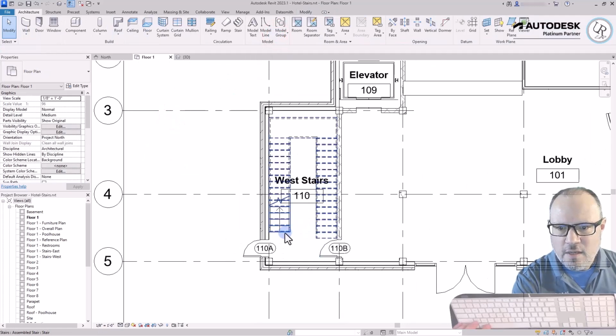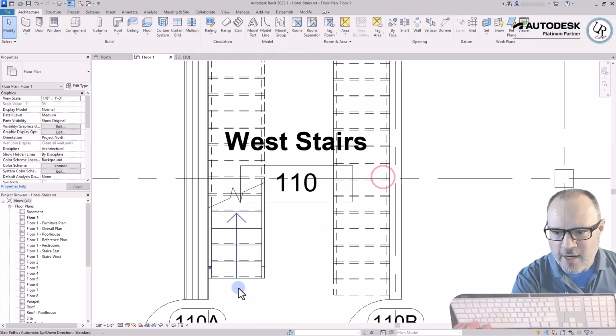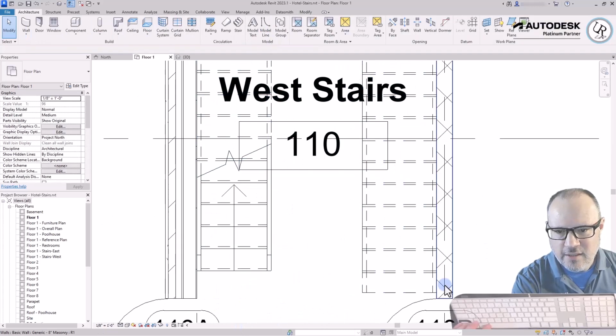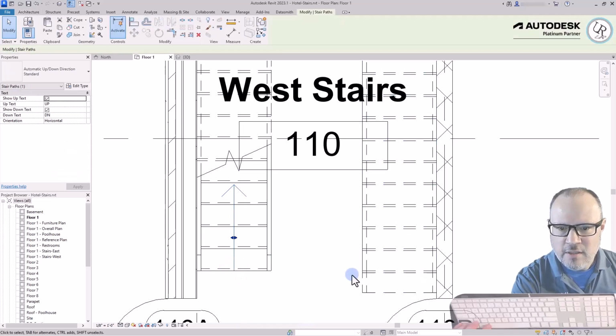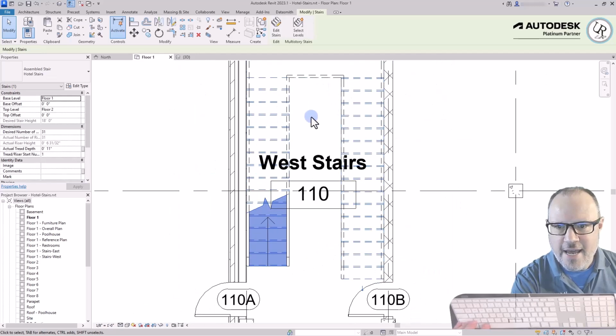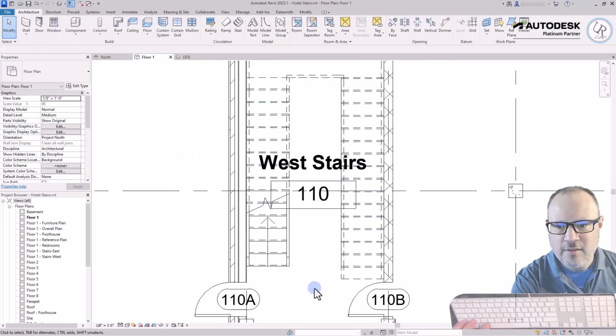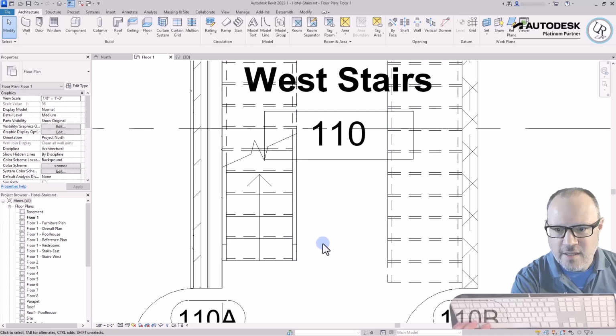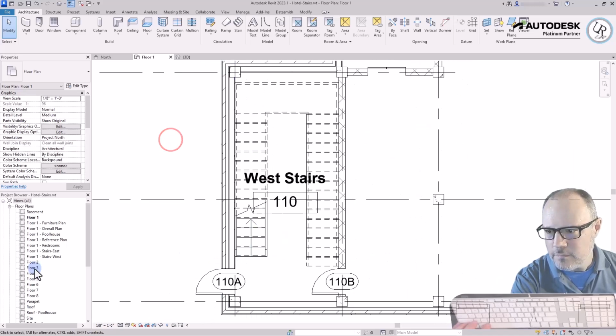So notice in the floor plan that it creates the stairs fully and intact from the up location, showing where it would exist on the floor above. In dashed lines it shows an overhead condition, and then solid lines in the area below where the cut line exists on that floor level.